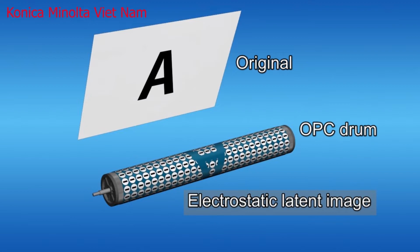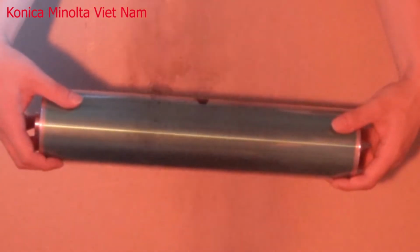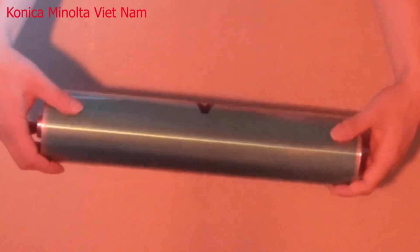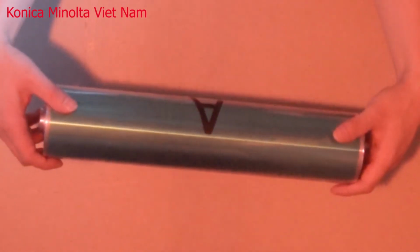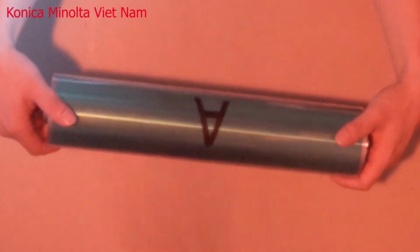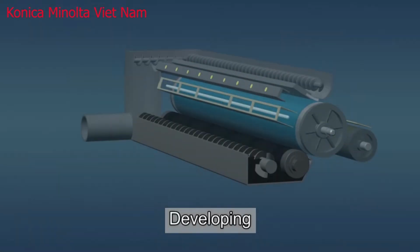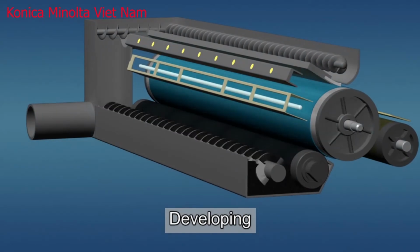Now, let's try an experiment. What will happen when we apply negatively charged toner to a drum with a charged image? As you can see, text is clearly visible. Toner adheres to areas where the charge has been removed. This adherence of toner is actually performed by the developing unit.